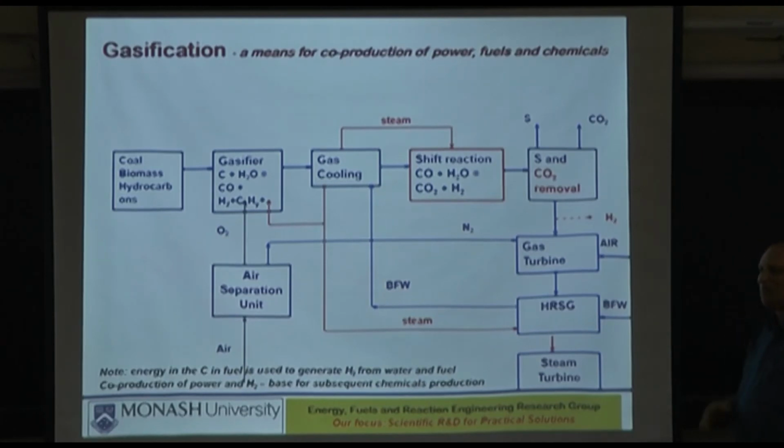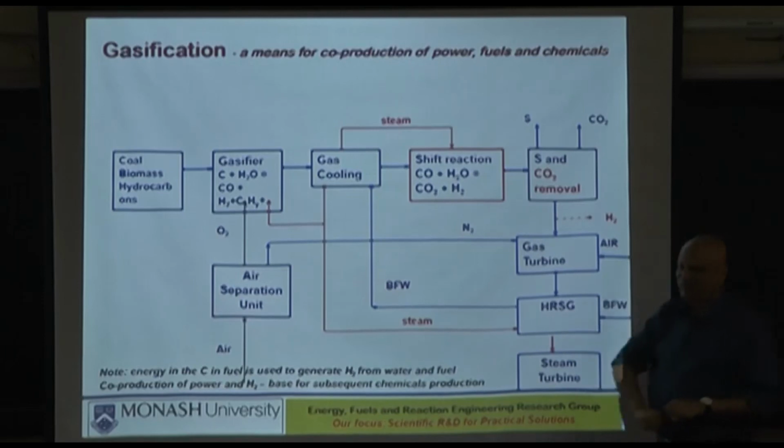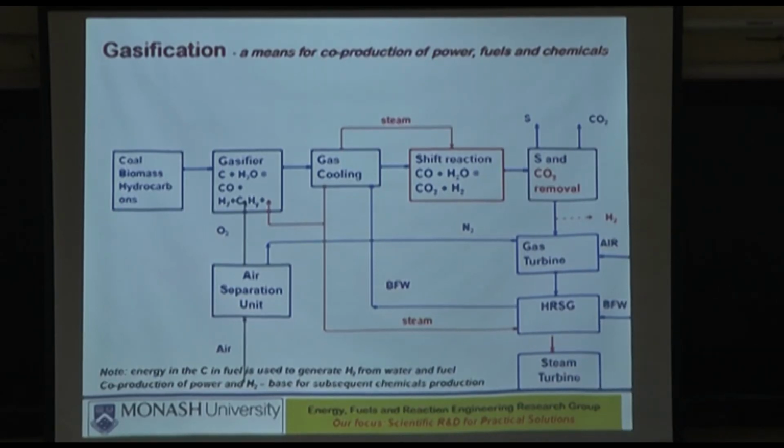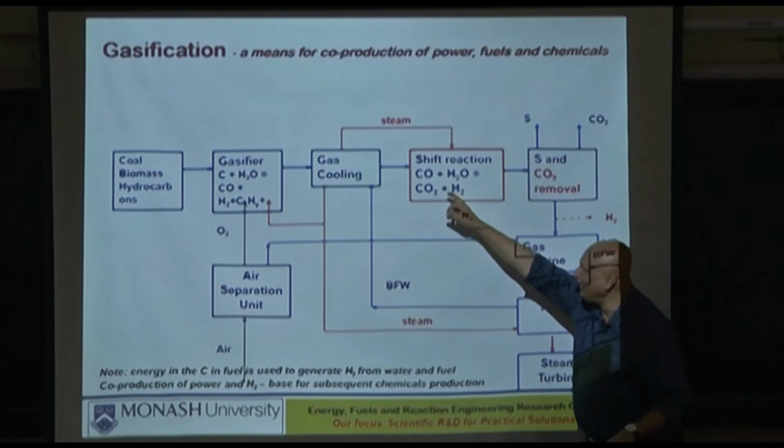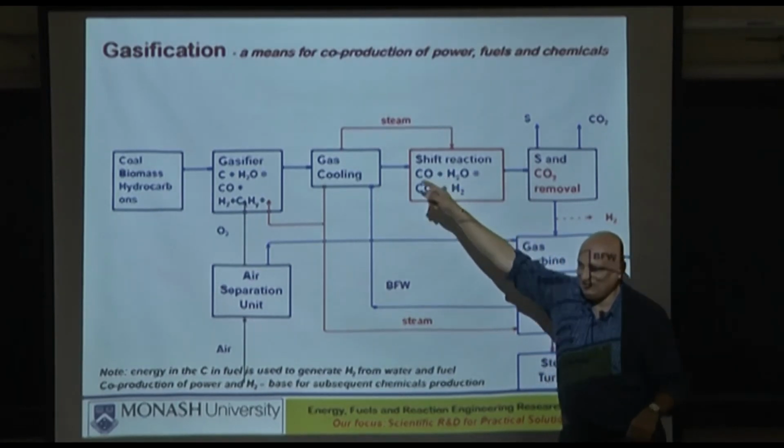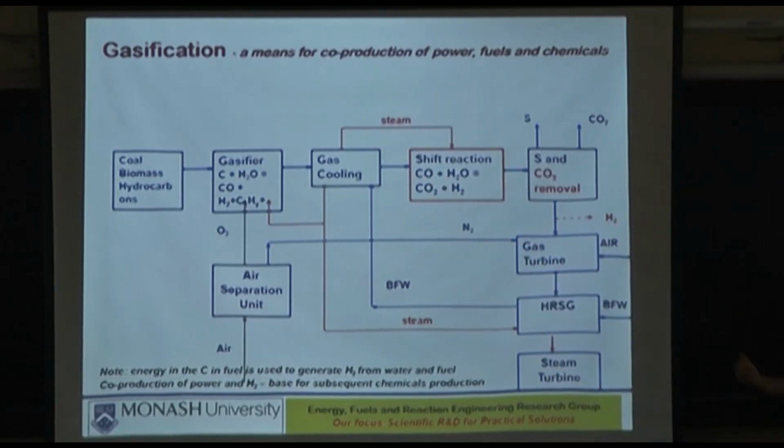In order to get more hydrogen than that, you have to rely on this separate reactor. Even there, how much additional hydrogen you will get will rely on how much you are getting in the first instance from the gasifier. That itself is related to the temperature of the gasifier. So, these are all to some extent interrelated. So, you are right.